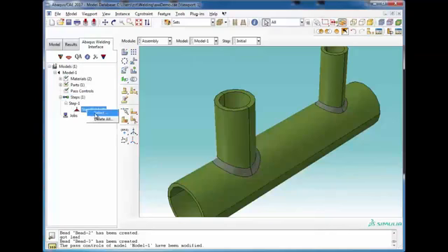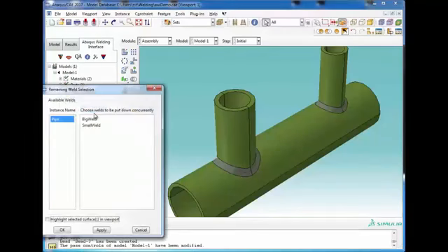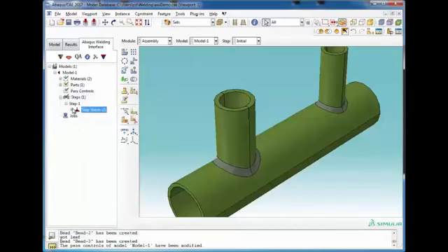And then the next step is to select which welds go down in that Abaqus step. Unlike the previous versions of the AWI, where it would take many hundreds of steps to lay down weld beads, in this version everything goes down in one Abaqus step. So I'm going to choose to put both the big weld and the small weld down at the same time. And now you'll see that this check mark is done.